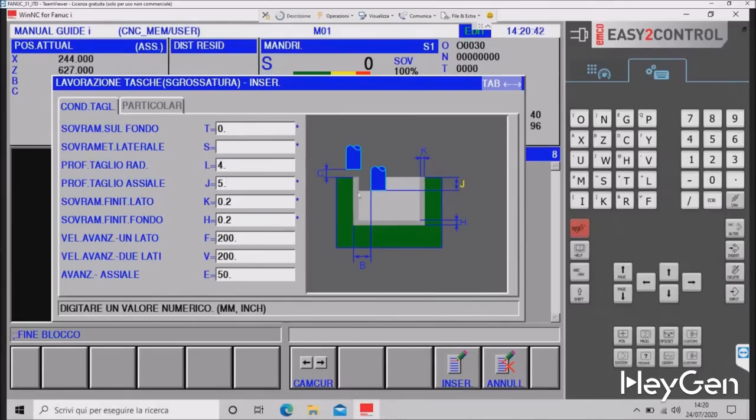Cutting data includes a feed rate of 200 mm per minute, depending on G94 or G95, with G95 set to 0.1 per revolution. Milling cutters work in mm per minute, and the feed rate is fine. When entering solid material, reduce the feed rate, e.g. set to 250, but it remains unchanged due to a manual guide limitation. ISO wouldn't have this issue. Entry feed rate from solid can be modified.